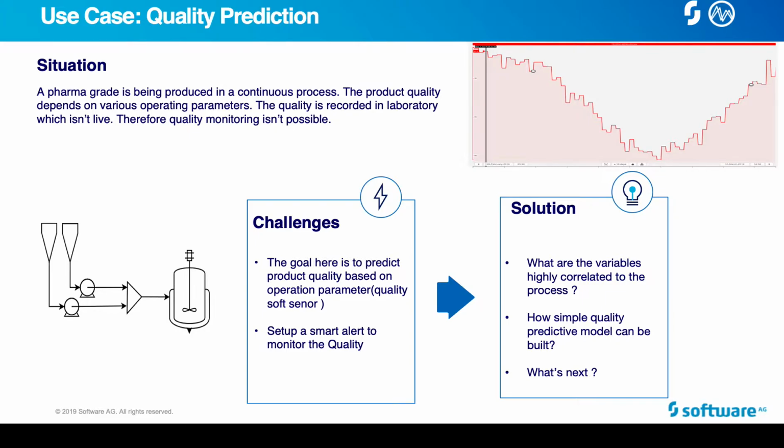So basically, if we trend quality data with the process data, then we can solve more and more problems, and that's what TrendMiner allows you to do. You can bring quality data from different LIMS systems to TrendMiner, and you can trend it with the process data. Another point here is that lab analysis is done a few hours after the process is done, so there is a time shift in that data.